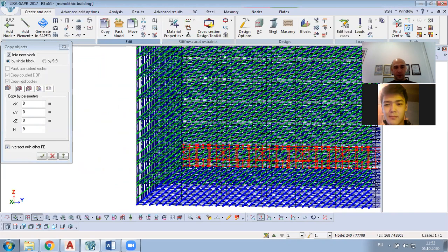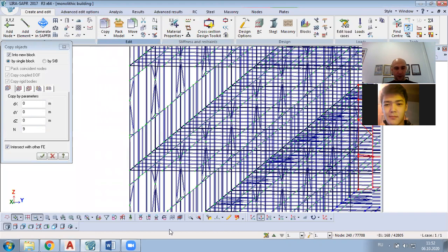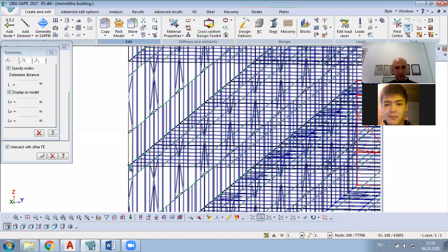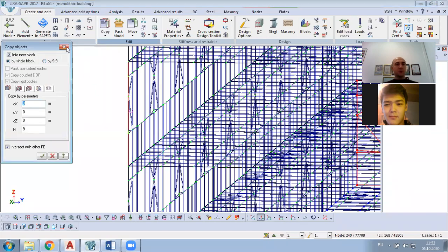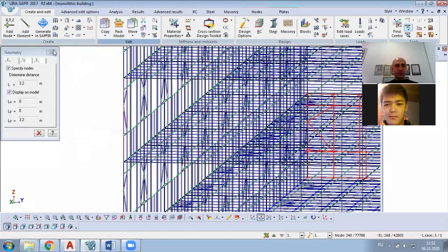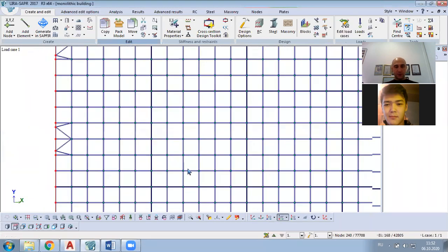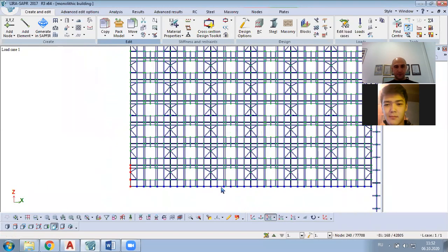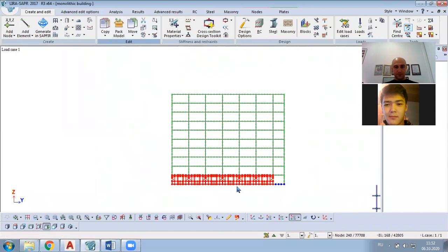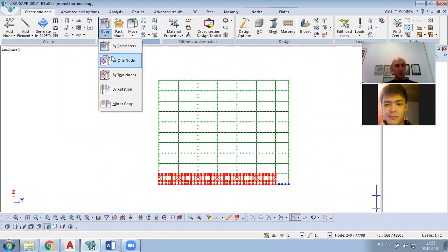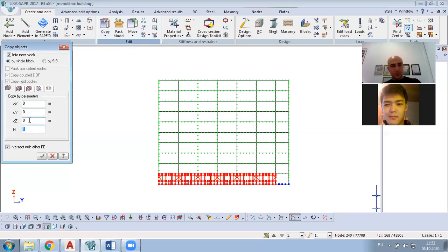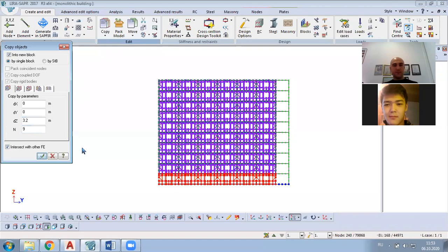And the height of my story is 3.3 meters. Copy in the Z-axis, nine times. Okay.